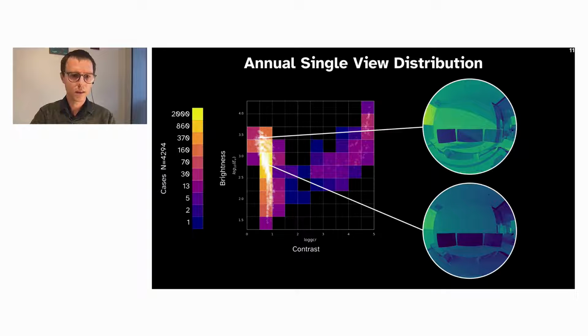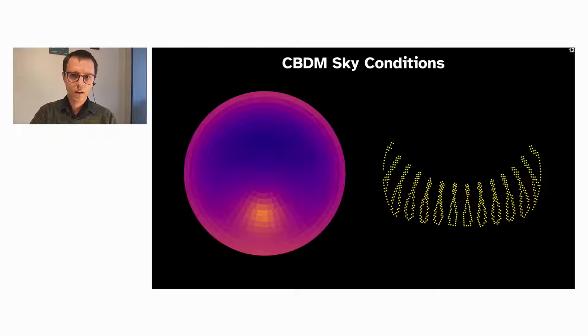building occupants. In addition to using a physically plausible rendering algorithm and sky conditions as already discussed, the distribution of evaluated positions and directions must also be representative. This can either be achieved by sampling from these underlying distributions or by knowing the proper weight of each sample. The daylight coefficient techniques underlying most climate-based daylight modeling workflows are effectively a uniform survey of possible sky conditions and sun positions. The application of a sky matrix reweights this to be more representative of the site.